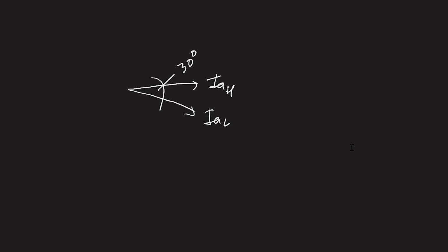So if we use a matrix of 1 for the low side, we're going to rotate it such that it now becomes, and let me switch colors, it now becomes in phase with the high side. So that way we're compensating for the phase shift across the transformer. All right, so now we've compensated for both the current magnitude and the phase shift across the transformer.